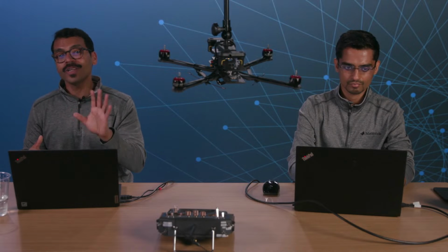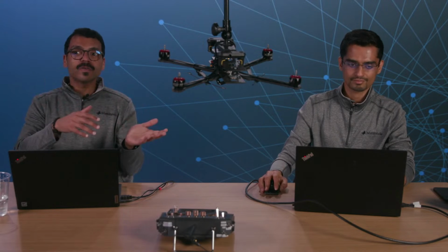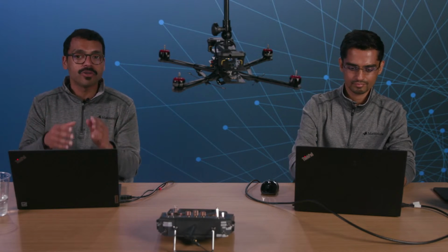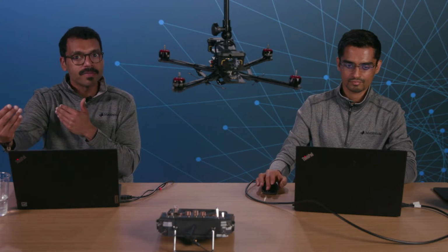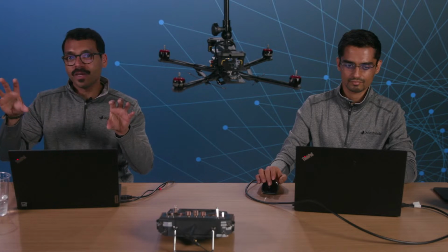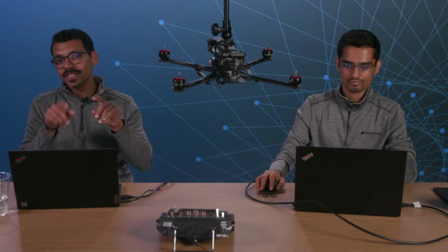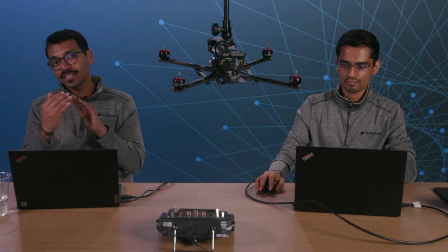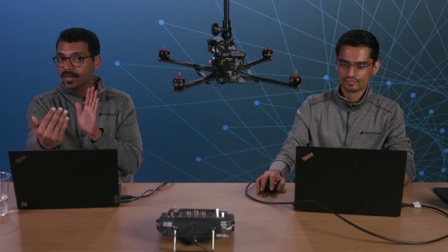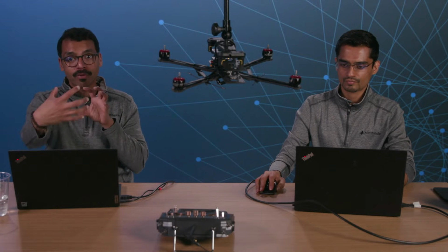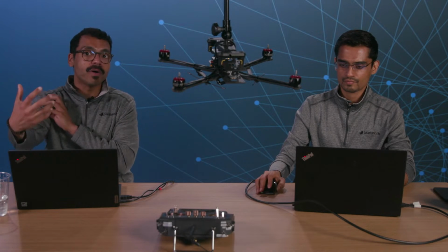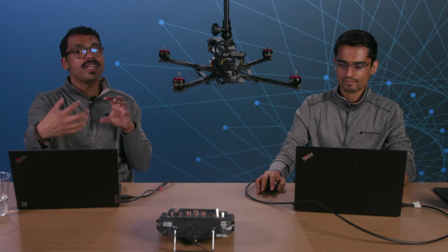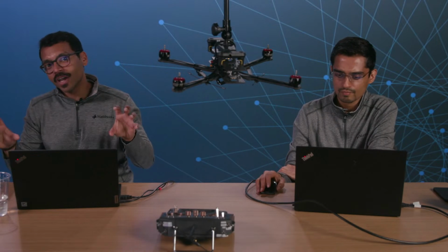A camera, which is really good at telling you what things are, but not great at telling you how far things are. So we use image-based or frame-based detectors to identify what an item is, and then we use LiDAR data to say, what's the depth of that item? So when we have a car versus maybe a truck, we can look at our camera and say, this looks like a car, and then take the LiDAR data, see how deep that car is, and then create a bounding box, a cuboid, that we fit around it. Similar to that, we can do it with a truck. So now your bounding boxes can change in 3D based on your camera's inference and then your LiDAR detector's inference.